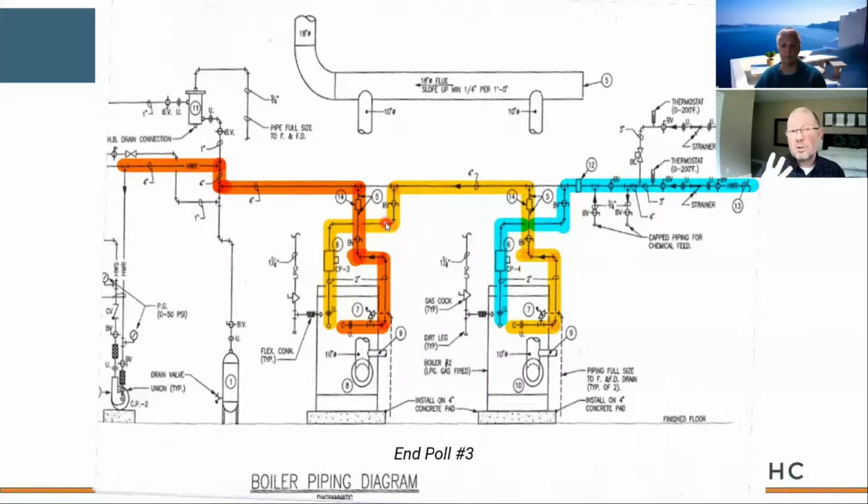Now, we've seen 4 boilers in series. We've seen up to 6 boilers in series. And the problem is the boiler closest to the return has 1 million hours on it because it's trying to carry the load. The further down the line you get, those boilers typically have 1 or 2 hours on them, simply because they can't operate very long before they spike on their own high limit, because they're getting influenced by all the other boilers that are sending hot water its direction. Okay, so boilers in series.